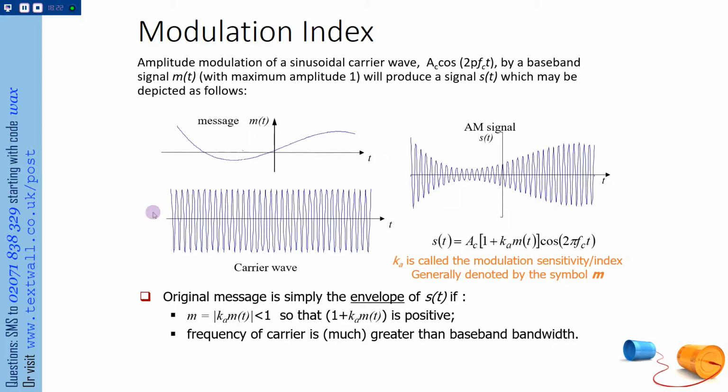Imagine that carrier without any change in its amplitude, just a constant carrier. There's no message. And if I start impressing the message upon the carrier, its amplitude starts changing. And I can keep increasing the depth of modulation until the amplitude has a significant variation. That's called the depth of modulation, and that's your modulation index. It's the product of m times Ka.